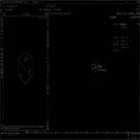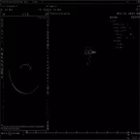To get started, dive into the Geo1 node, get rid of the file sub, and lay down a torus. To have some geometry to work with, let's up the subdivisions to, say, 24 and 48, just to have some geometry.